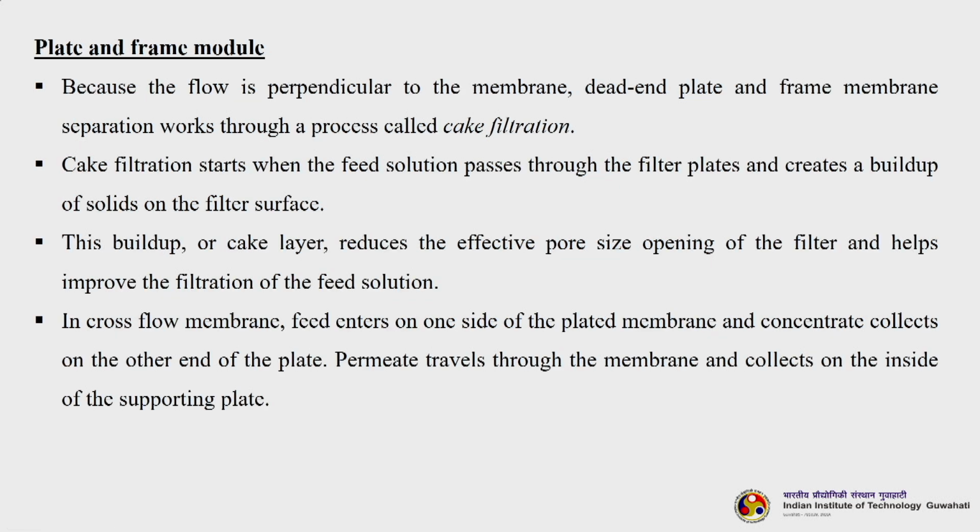Because the flow is perpendicular to the membrane, the dead end plate and frame works through a process called cake filtration. The cake filtration starts when the feed solution passes through the filter plates and creates a build up of solids on the surface. So, basically on the membrane a cake starts to build up, and some sort of concentration polarization is happening. Then as the layer grows, you get a cake layer. This build up or cake layer reduces the effective pore size opening of the filter and helps improve the filtration of the feed solution.